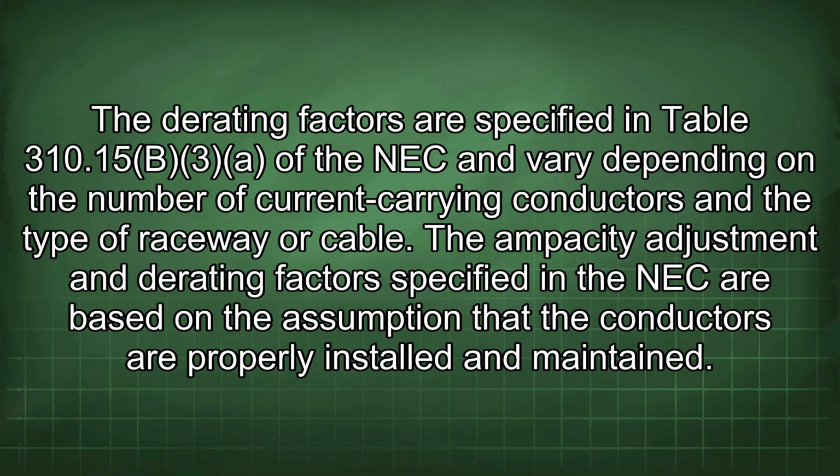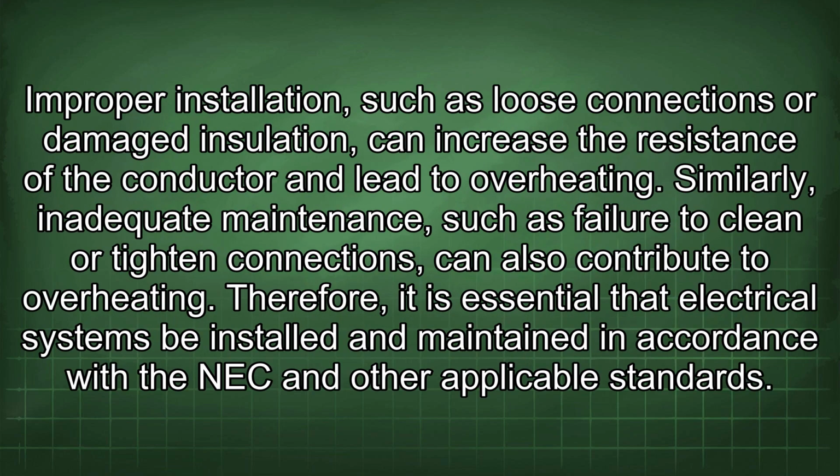The ampacity adjustment and derating factors specified in the NEC are based on the assumption that the conductors are properly installed and maintained. Improper installation, such as loose connections or damaged insulation, can increase the resistance of the conductor and lead to overheating. Similarly, inadequate maintenance, such as failure to clean or tighten connections, can also contribute to overheating. Therefore, it is essential that electrical systems be installed and maintained in accordance with the NEC and other applicable standards.